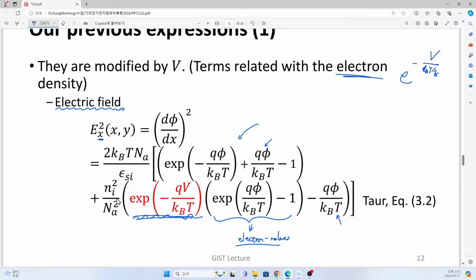It means that, yes, if we have positive electrostatic potential, and of course this red colored one will give us an even smaller value than the positive number 1, and here we have a minus sign, and this one gives a small number. Please note that the coefficient itself is already quite small, and our electrostatic potential should overcome that small coefficient to get surface inversion.